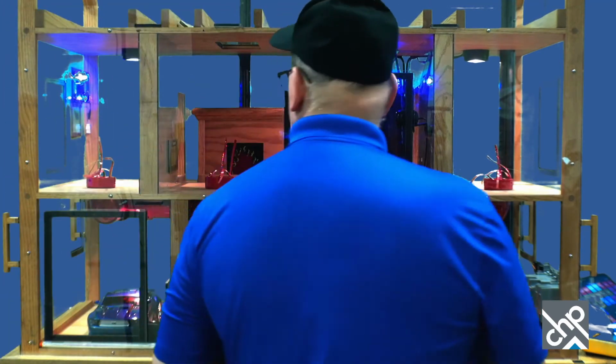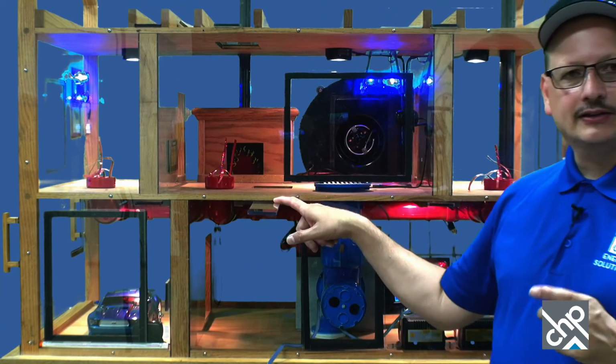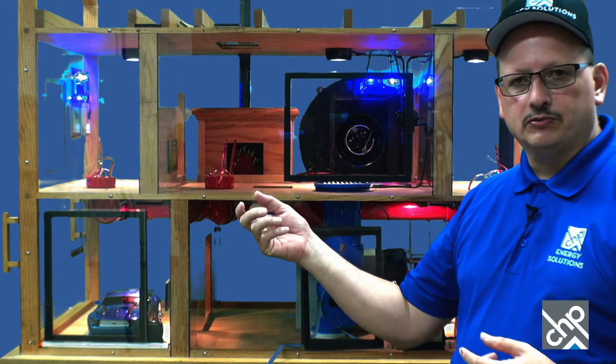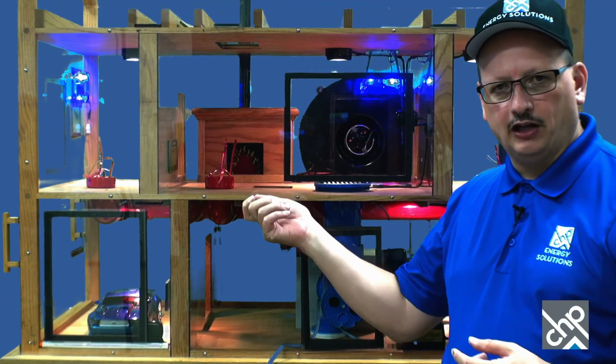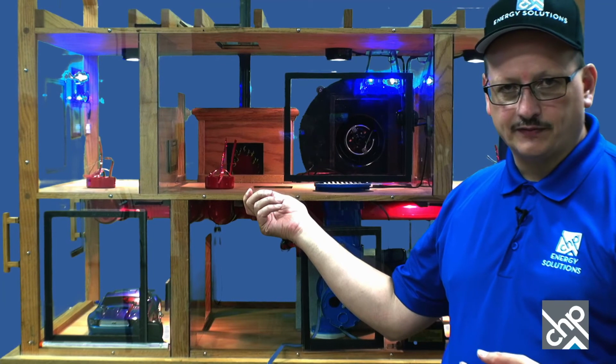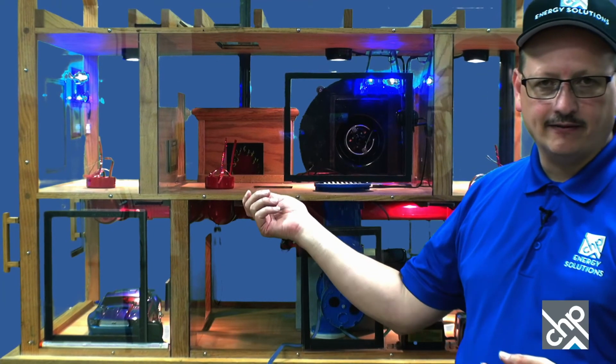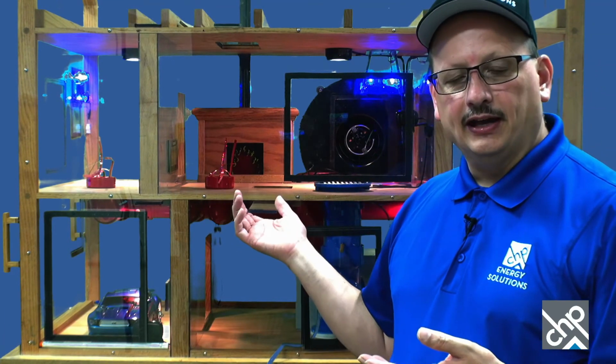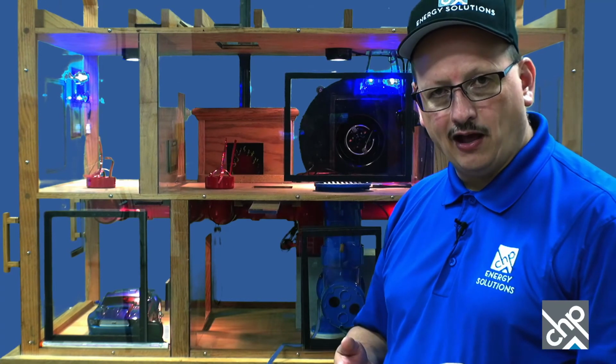Now, this is what I was talking about before, though. We have a door between the CAZ and the house. So what we'll do is we'll do it once at this door open and once at it closed, once when the exhaust fans are on, then when the air handler's on. So we'll actually have 4 tests this time. We'll have exhaust fans with the CAZ door open to the house, exhaust fans with the CAZ door closed to the house, and then air handler with the CAZ door open and air handler with the CAZ door closed. So we'll have 4 numbers, and you would take the most negative of those numbers.